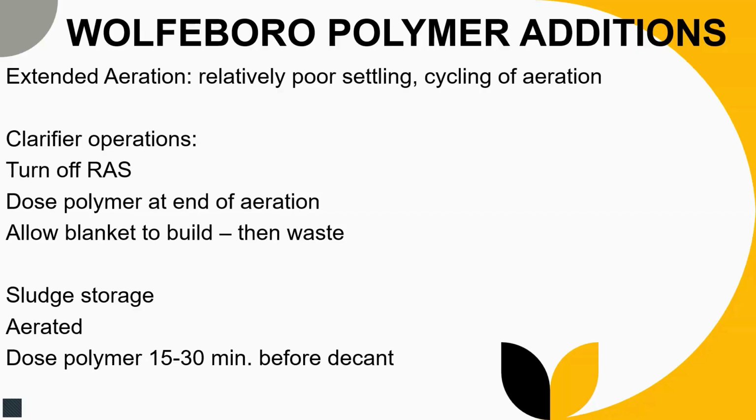So that they don't get that septic condition where you get phosphorus release from your solids back into your liquid stream processing. So I was like, this is really cool. They have really good numbers. I think their phosphorus is averaging about 0.7 without any metal salt dosing. That's really, really good for the type of plant they have.